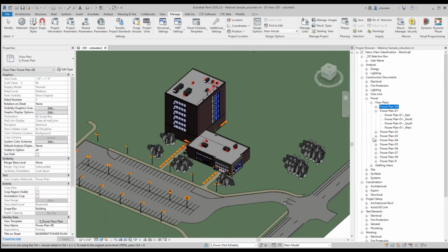And the Dynamo script will strip out everything that you don't need. So if this were a real project and I've only got 2 levels here, I would only see level 2. And this building isn't big enough to be split up across multiple sheets, so I wouldn't have the dependent views. They would all be gone. So it's not a tedious task to set up a new project.